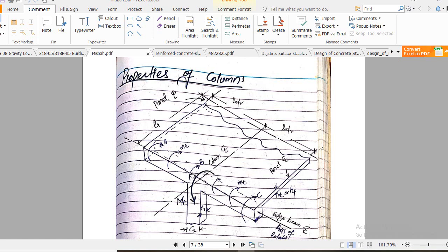So the column prevents the slab from rotating, but the effect of the column in preventing the rotation of this transverse member is dominant in the region near the column, but far away toward the center line of the panel it decreases. So that is why the section will rotate highly. You can say there will be more torsional strains at point A and at point C as compared to B.